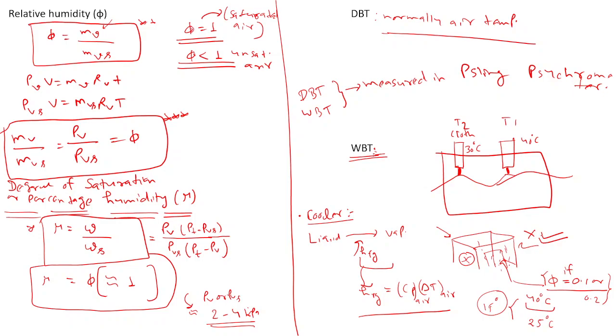Yes, sir. So what is the wet bulb temperature here then? Now again listen. Here air at 40 degrees Celsius came and absorbed water vapor, converting liquid to vapor. To convert that liquid to vapor we have to give some amount of latent heat, and that would be given by the air.